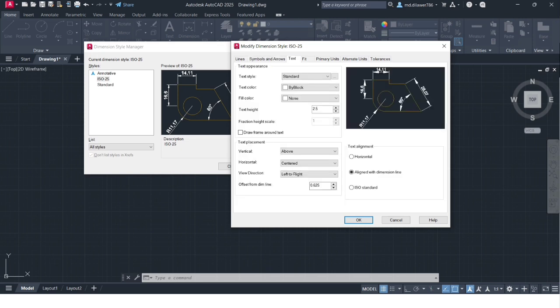Next, text height is also important. If the text height is very low, you are unable to read the text, right? So my suggestion, use text height 5. Wherever you require, the text height can be made bigger. For example, you have drawn one rectangle, and we are going to draw the diagrams in the rectangle.